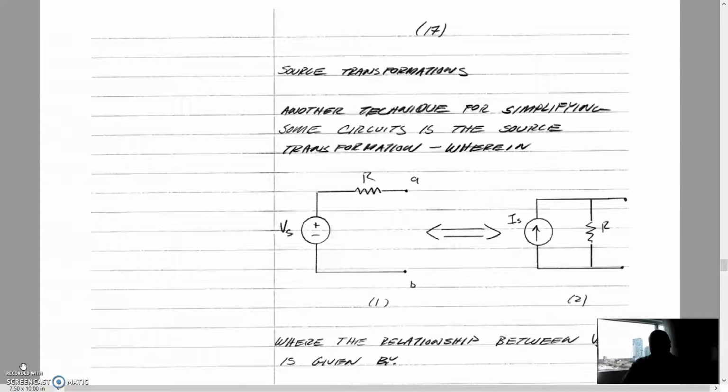You're going to build equivalent circuits, but just like in the case of combining resistors, once you combine those values, if you want to solve for something from some previous iteration of the circuit, you have to unpack the circuit and do a series of voltage and current transformations to unpack it. So normally, if you want to know everything about a circuit, use one of the techniques we've already talked about. If you want to know something about a load connected to a circuit or about the impact of a particular value on a circuit, that's where source transformations come in handy.